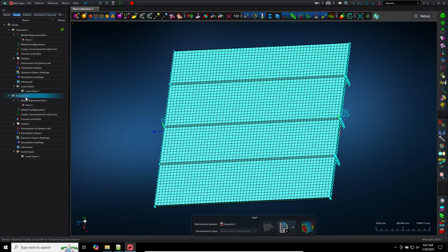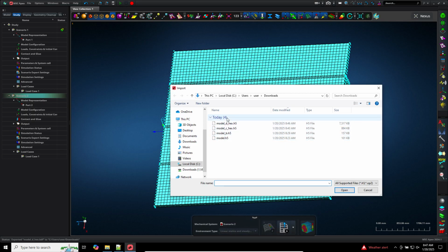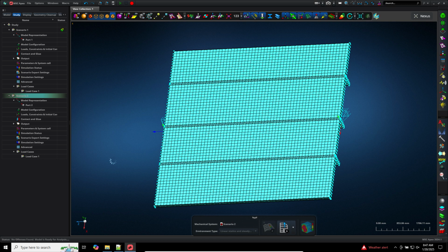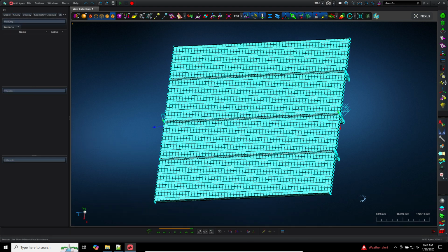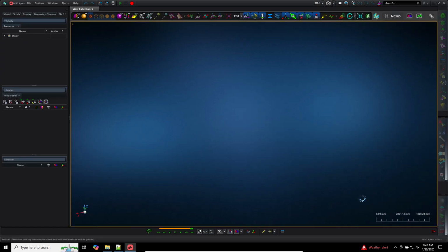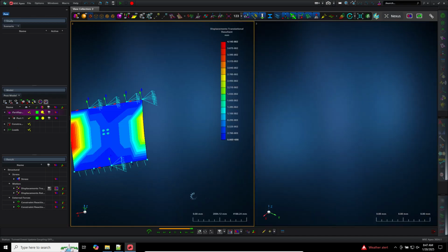Now what I can do is go to that scenario, right click on that scenario, click attach Nastran results, go to browse, go to, here we're working with model D, click attach. Now, once it's attached, the H5 file, we get this message, attach Nastran results successfully. Click on this post-process icon. And now I can look at the deformations or the stresses for this model.